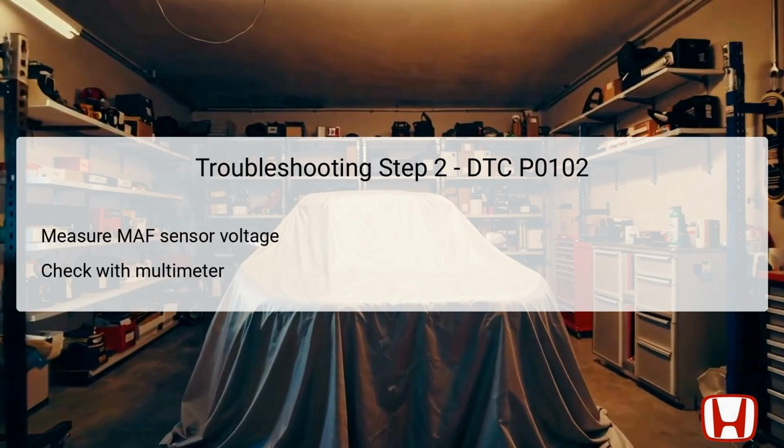In the second troubleshooting step, use a multimeter to measure the voltage output of the MAF sensor while the engine is running. This provides confirmation of whether the sensor is providing an adequate voltage reading to the PCM. An expected reading should be well above the malfunction threshold of 0.10 volts.